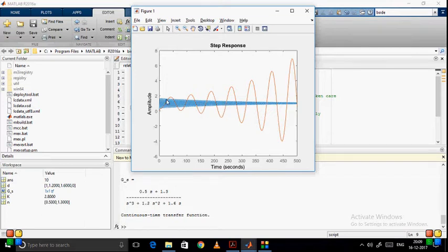You can see that at 2.7 the oscillations are damping, that is, reducing. But at 2.8 the oscillations are increasing, which is just the reverse of what happened earlier. So it suggests that at 2.7 the system is going to reach its final value, so that is a bounded output, whereas for 2.8 it becomes unbounded, because you don't know what the value is, it keeps on growing.